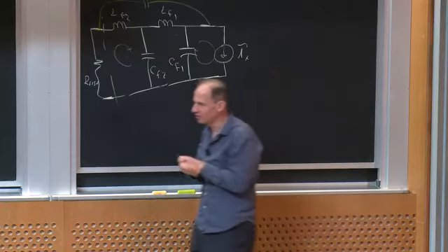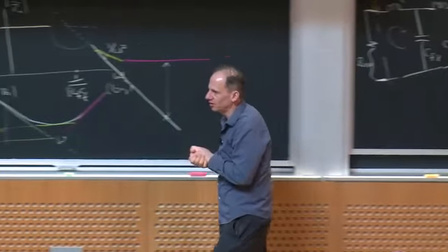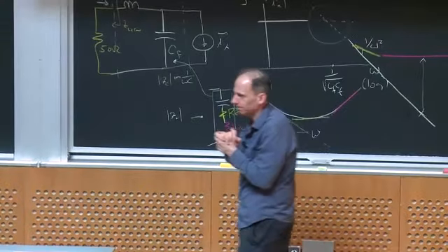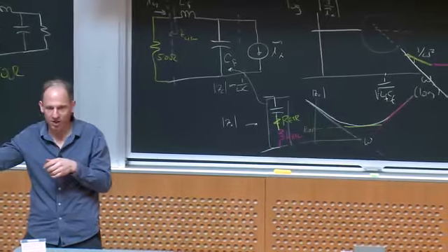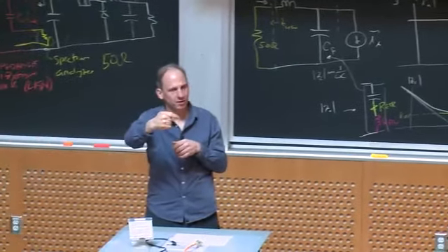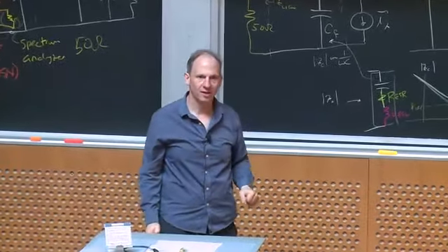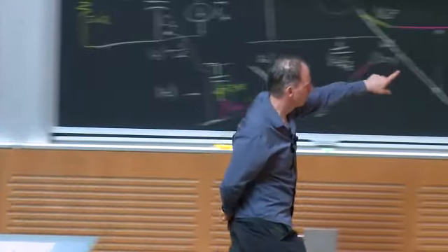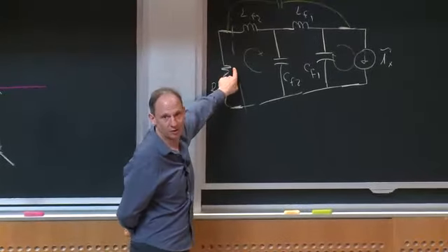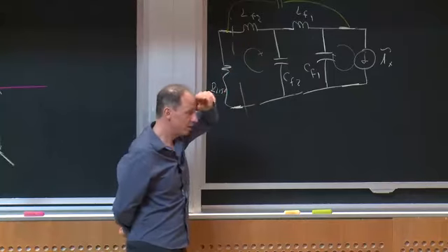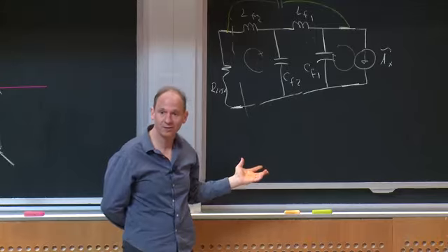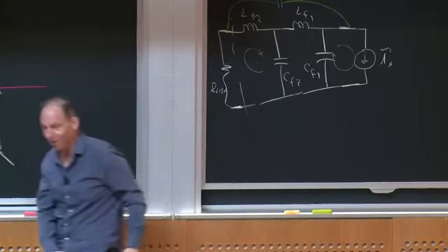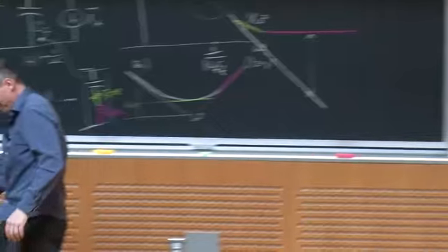And we have a demo of this. What this is essentially is a set of 4 filters here. These are just LC filters. And I'm going to let Rafa demonstrate. What we have is a network analyzer. What a network analyzer does is it drives at one port, which would be like our signal in, and then it measures into another port, which would be like our signal out. Okay? And let's see the effect on the performance of the filter. It has the same physical components, just placed slightly differently. And with that, I'll hand it over to Rafa and let her explain.